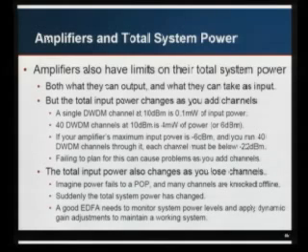And also remember that the total input power can actually change when you lose a channel. So say for example you have a 40 channel system and 20 of them are in a path that loses power. Boom, you just lost a whole bunch of optical power in your system. So what happens is people engineer the amplifiers to do dynamic gain to maintain a working system level. But it's a lot more than just amplifying the signal. You need to kind of engineer it to keep it within these constraints.